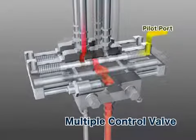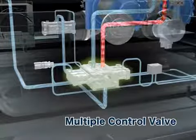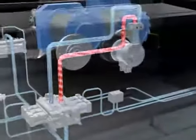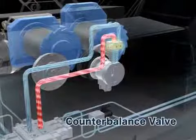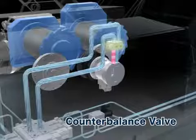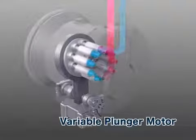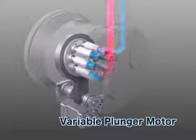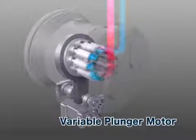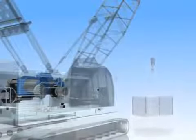Based on the position of the spool, an outlet port is selected, and oil is then sent to the variable motor's counterbalance valve. Hydraulic oil passes through the counterbalance valve and heads towards the variable motor, where its pressure then rotates the motor. The drum rotates along with the motor, hoisting or lowering the load.